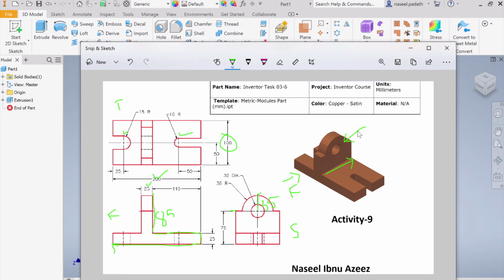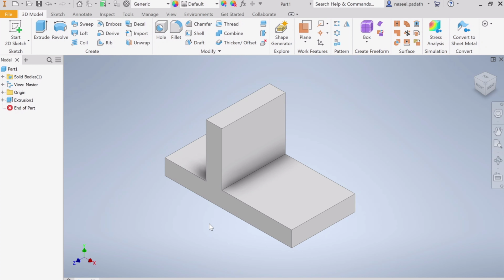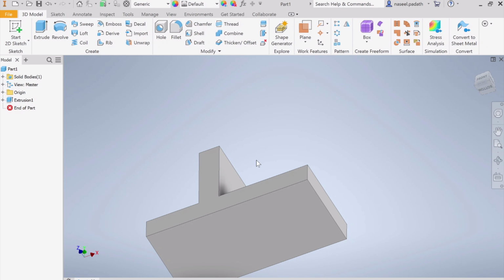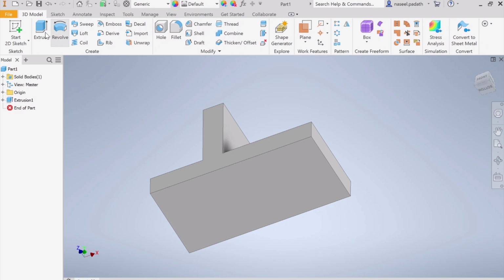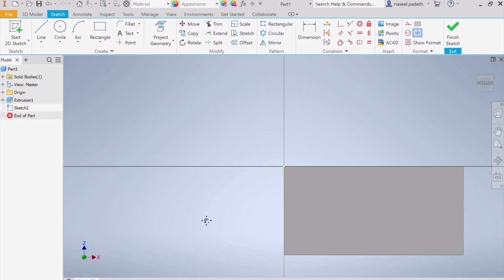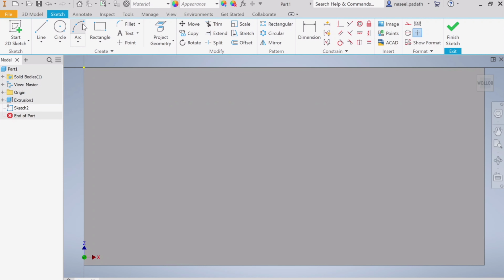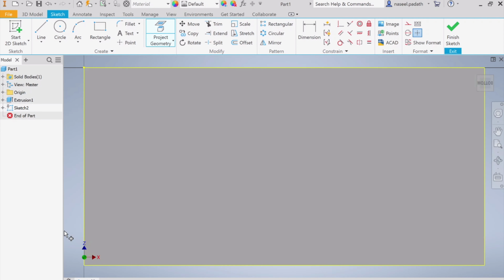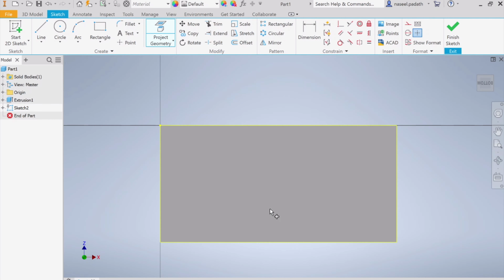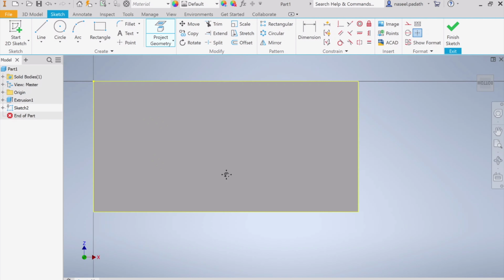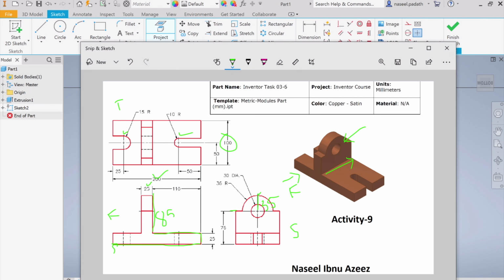Over here we have a solid, so it's better I'm going to choose the bottom, and I will make this sketch. So go here, hold the shift button, click on wheel, rotate it, click on wheel to move, and start 2D sketch. I'm going to choose the bottom and arrange it. Maybe you can click zoom all, and now project this plane in order to get everything properly. And then let's check the sketch.